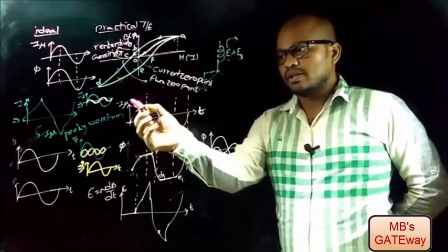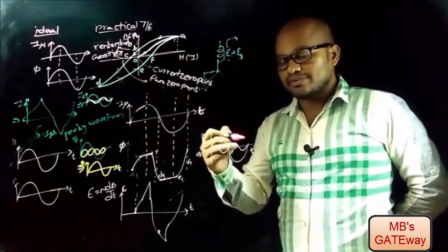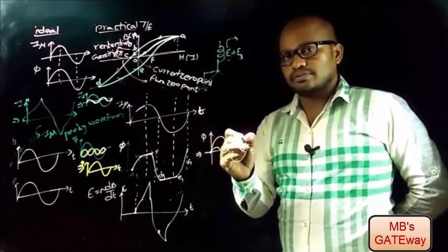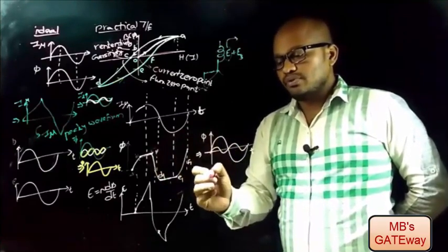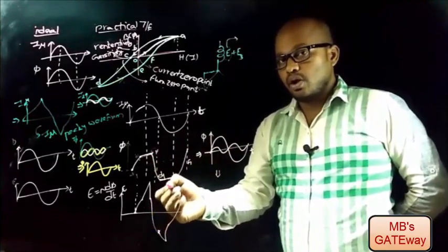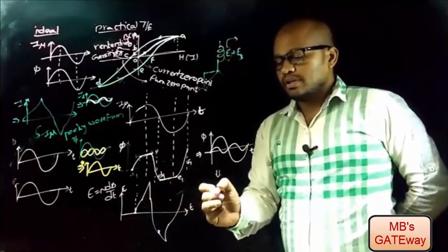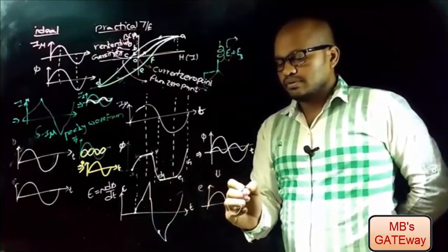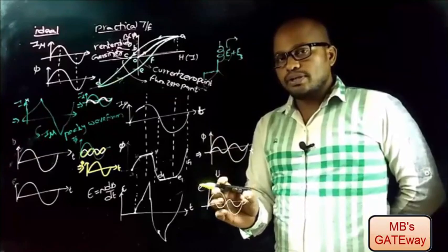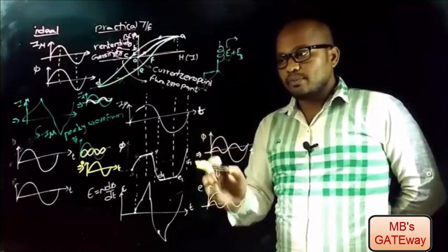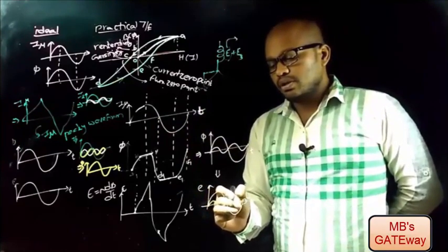Because of the sinusoidal current I mu, this is the sinusoidal flux, and because of the addition of harmonics by the transformer, this is the harmonic signal, and combined we are getting a non-sinusoidal signal, because of which we are getting a non-sinusoidal output EMF. And this can also be represented with a sinusoidal signal and a harmonic signal. Now the discussion is how to get sinusoidal output from the transformer with sinusoidal input. For that we need to reduce this third harmonic signal to 0.